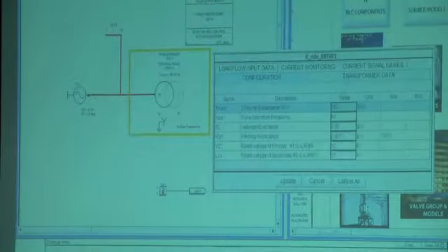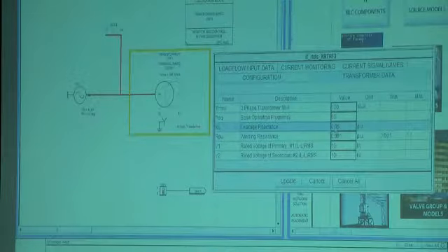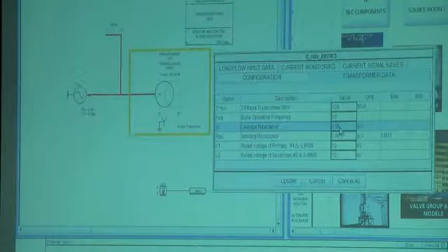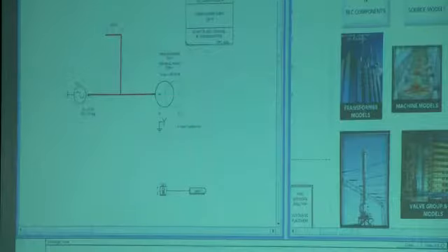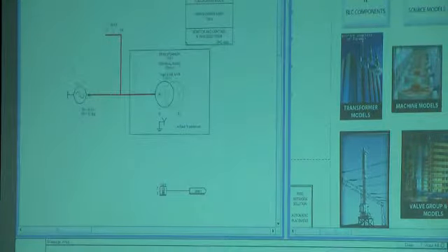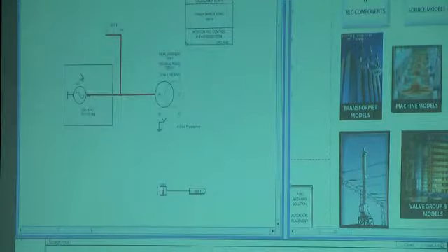Again, you need to make sure that this leakage reactance isn't too small, because if it's too small, the capacitance that gets added is large, and it can cause some numerical problems. Typically in a transmission system, you'll have a line that's long enough to split, more than 15 kilometers.